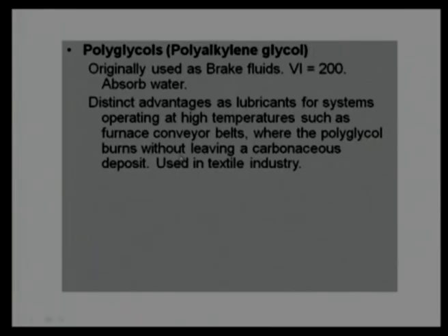Another thing is that they have good cooling capabilities, which are desirable. In addition, in a high temperature application, if they start burning, they do not leave any debris or deposits. So, they are clean liquids, they vaporize, and they do not show that these kinds of lubricants were there at all. So, they can be utilized for the textile industries where cleanliness is a prime requirement.